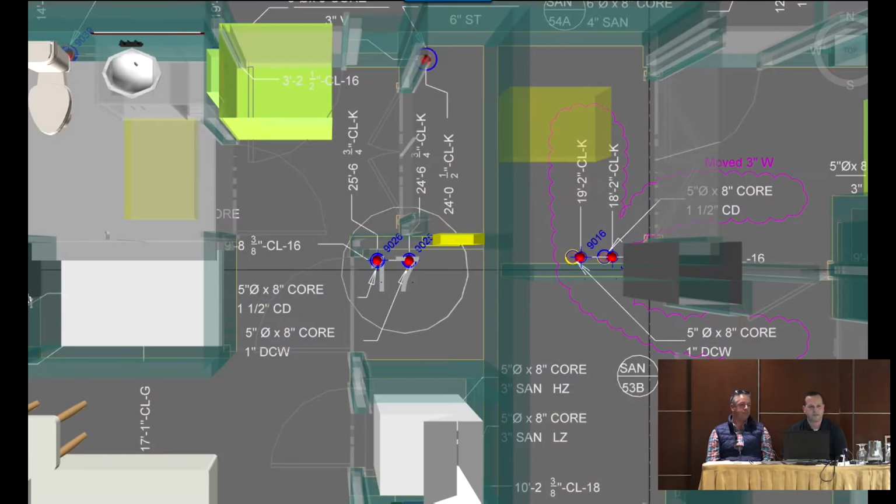All right, so how do we incorporate all this together into Navisworks, which is what we use? Obviously, we're not going to talk much about clash detection, MEP. We're doing all that already. This is sort of a further step. What you see here is basically that we're asking our trades to annotate their files early. We have a certain diameter system coming into play, and we really want to know what core diameter you need for that system. So if you have a 6-inch pipe, do you need an 8-inch core? That's what the structural engineer wants to see.